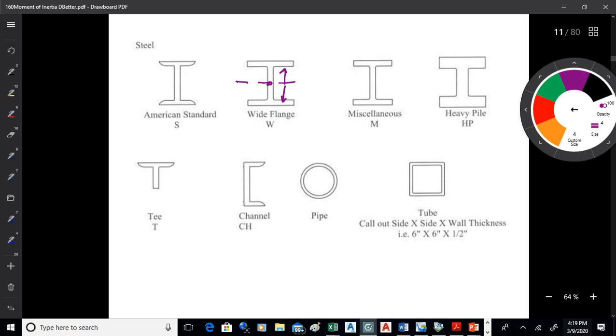If you look at columns sometimes, they make them out of tubes and pipes. They bend a little differently than beams. They kind of bow one direction or the other if they're loaded. So you want to get that material out away from that central axis about which they might bow. If you want to get more stiffness out of them too, you just fill them with grout. That gets them a good bit stiffer too. Good trick, okay?